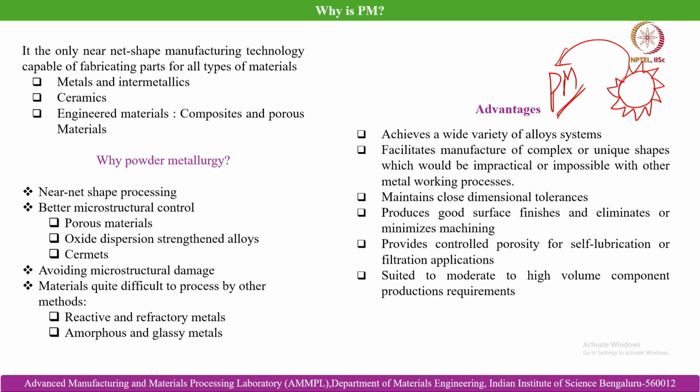So, as it is very much beneficial in case of small size, micro size components, it is not so in case of large parts, because in case of large parts you need to have large furnaces to sinter it, which often becomes uneconomical and not feasible also. So, in that case your conventional sand or permanent mold based casting processes become more useful.